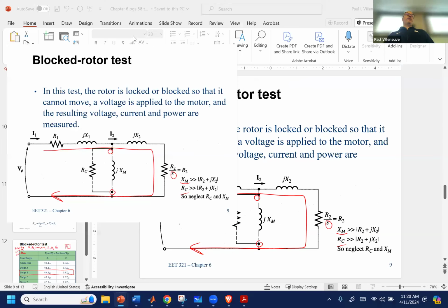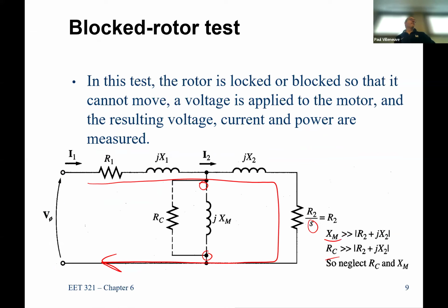All right. Anybody have any heartburn with these tests? Make sense? Happy with them? I hope not. Why? Didn't I just tell you you don't want a motor to be running at 5 minutes at heavy loaded conditions? You think that's a good idea to lock this in position and run it at full voltage and full frequency and then pray it doesn't burn out? Some of these are only going to last for like 5 or 10 seconds before they start to get some damage. So might not be a great idea to do that.